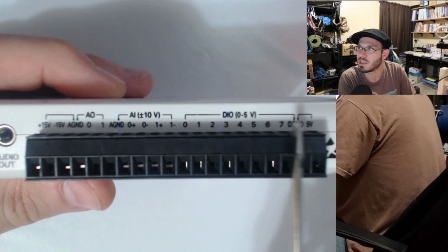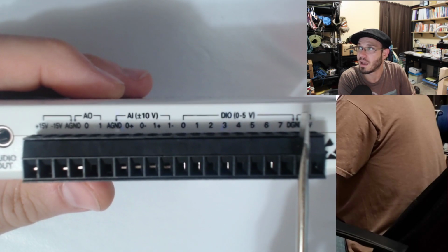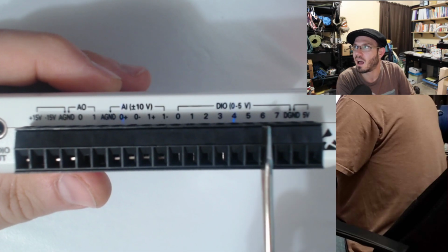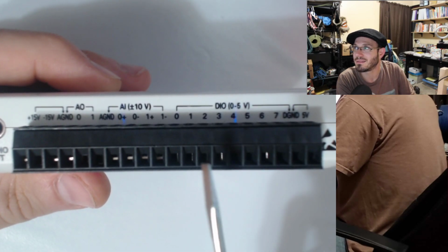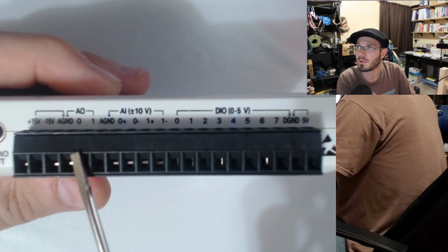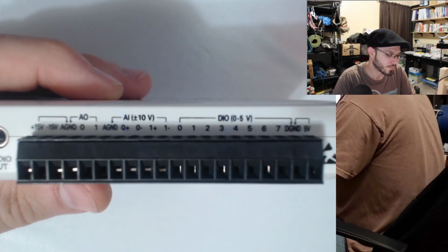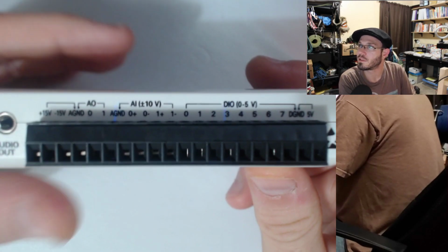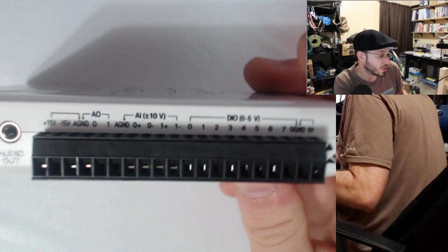And so let's only worry about the function generator and oscilloscope. There's a lot more functionality that you can get out of this device. It can also behave like a logic analyzer and quite a few other functions. But let's just focus with the oscilloscope and the function generator for now. So what I'm going to go ahead and do is I'm going to hook up some wires just like you would on your bench.